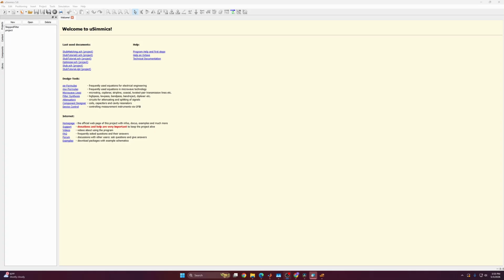Then we'll show the layout tool, a stub, and optimizing a stub for a specific capacitance at a specific frequency, and then the use of the SNP block to ultimately create a matching network or show that a matching network works. All the calculations and legwork was done off video. So this is really just a tutorial on how to implement your design in QUCS.